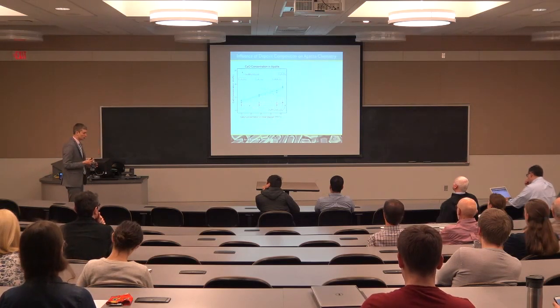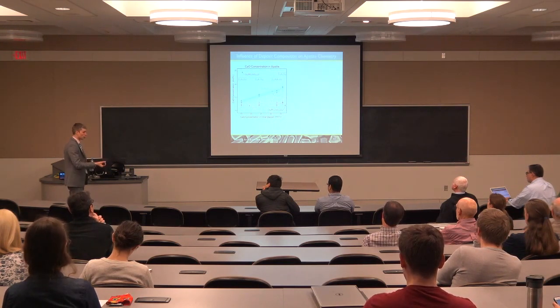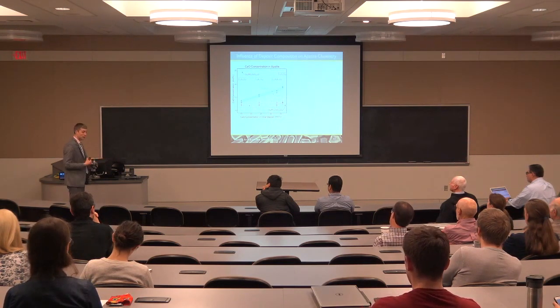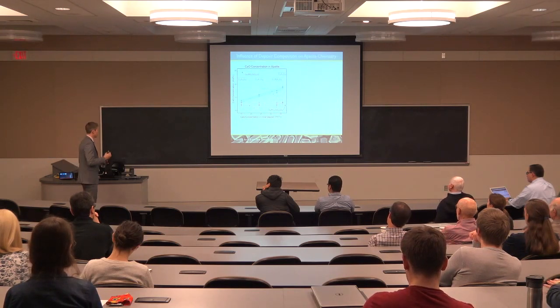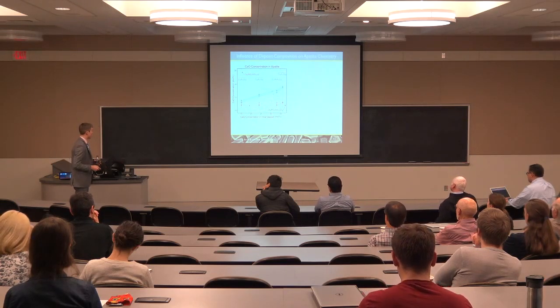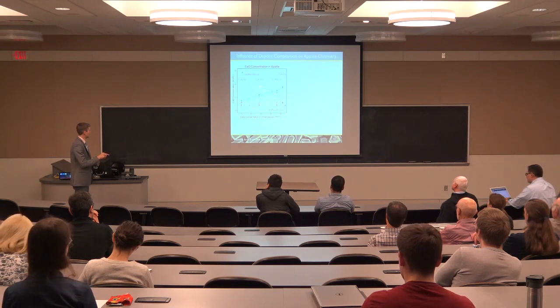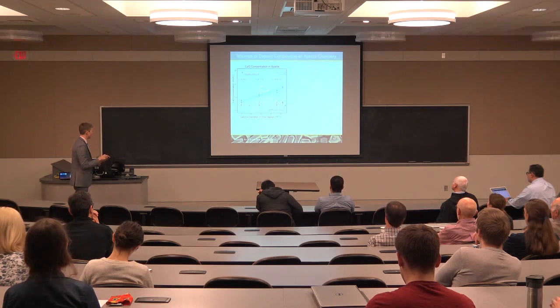the amount of calcium in the deposit, in the melt, the amount of calcium that goes into the apatite increases. And this would be good from the perspective that for every mole of rare earth that we put into the system, we're pulling more calcium out of the system, consuming more of the melt, increasing the volume of crystalline phases, which promotes or better seals the gaps that allow the infiltration to happen. And we see that in this case, there's not much difference between the yttria and the gadolinium composition. Even if there's maybe a greater driving force for the gadolinium to precipitate, the composition doesn't change a lot.